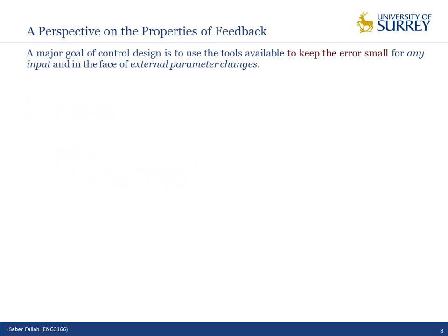We talked about the benefits, advantages and disadvantages of having a feedback or closed loop control system compared to an open loop system. What are the advantages of having a closed loop system or feedback system? Handles disturbances better. Yep, disturbance rejection. Robustness against parameter variations. Stabilizing the system if it is not stable. Okay, and better tracking, reference tracking.